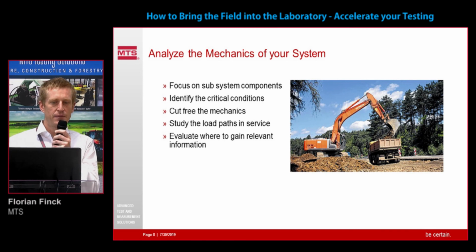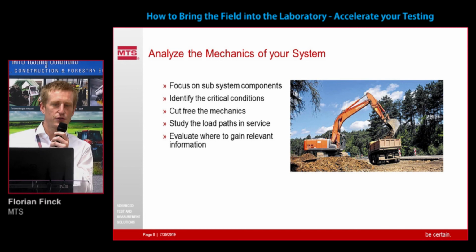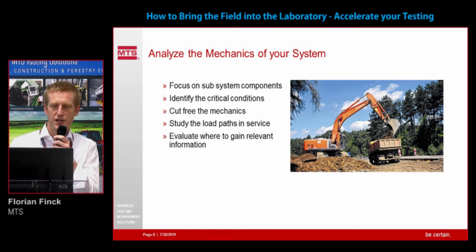And when you're doing a measurement, you might want to find the spots where you would gain relevant information. So when you apply strain gauges, where are the weak spots? Where do you have stress concentration? Where can you learn from your structure while you're doing a measurement?